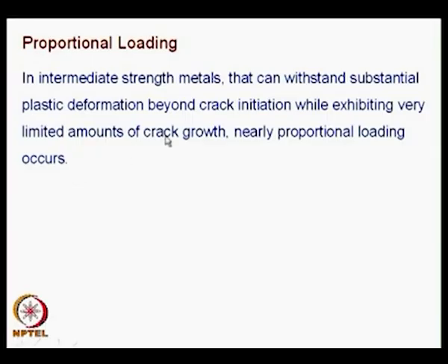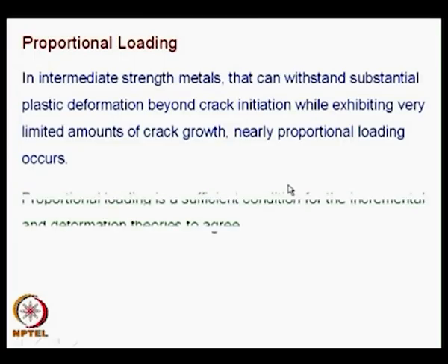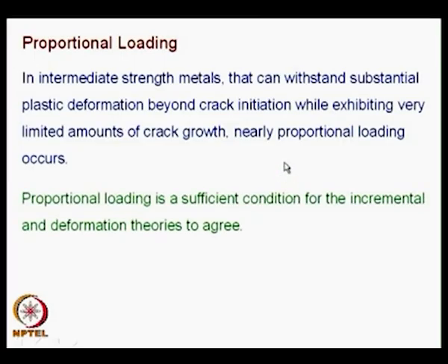The moment a crack grows, unloading takes place because you have formation of two free surfaces. When you have two free surfaces, the stress has to be redistributed. What we are trying to say here is that certain materials can withstand substantial plastic deformation, so essentially there is no significant crack growth. So, nearly proportional loading is possible, that is the way we have the approximation, and this is again re-emphasized.